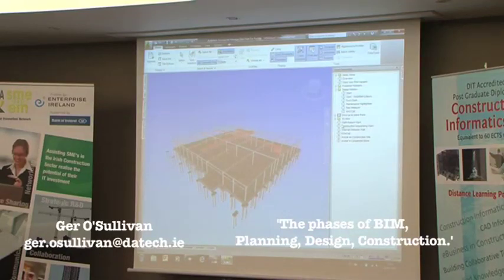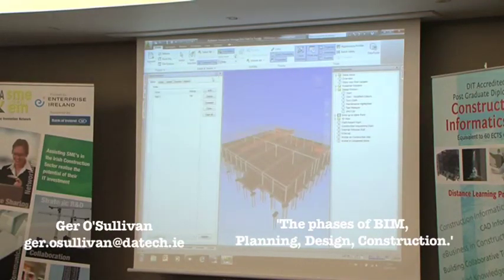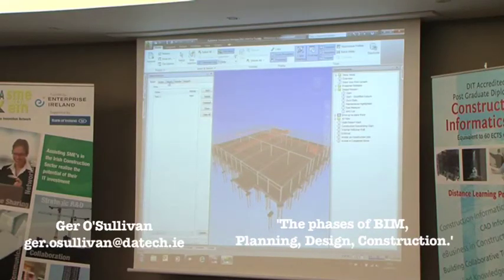Okay, so if we just look at a view with those, we can then go to our Clash Detective and just clear existing ones that I may have created previously. Let's go to our selection tab, and we can then decide, well, we'll clash the structure against the MEP model. We're just looking at hard clashes here. We can also do clearances, and we'll just run the clash detection. So there are thousands of objects in this model, but fortunately, we've only got 38 clashes.